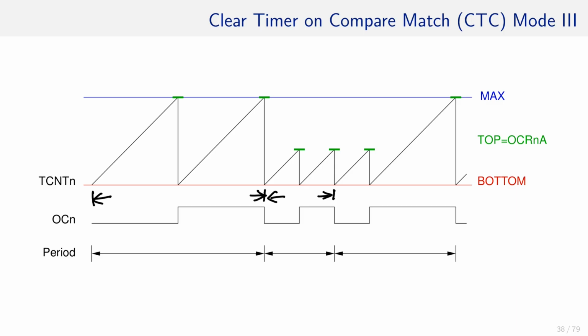Depending on what the ATmega is used for, some peripherals need an external clock input. The CTC perfectly allows to generate such a signal with an equal time for the low and high section of each period. If a faster clock is required, a lower top is used, while a higher top value results in a slower clock and therefore longer period.